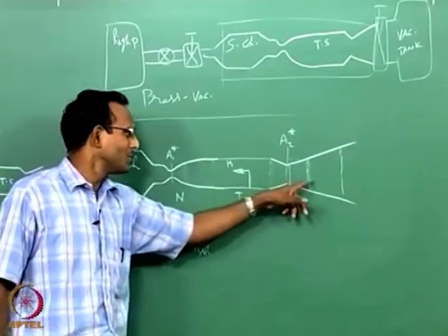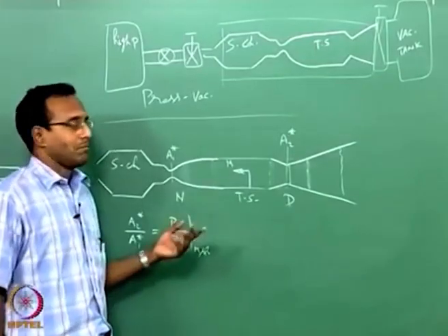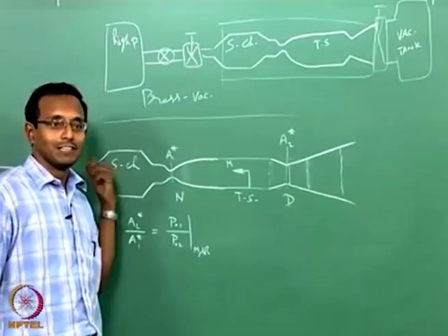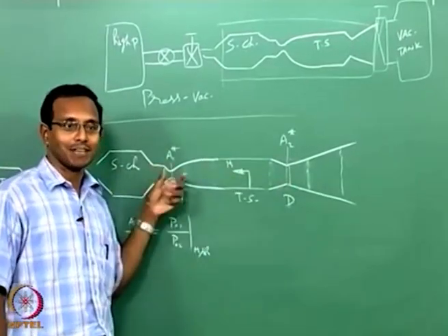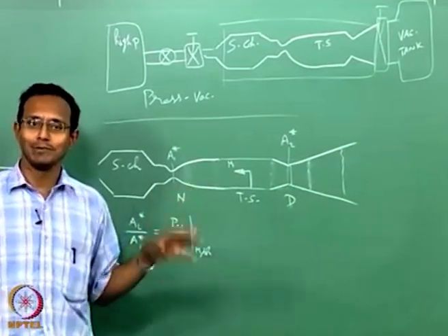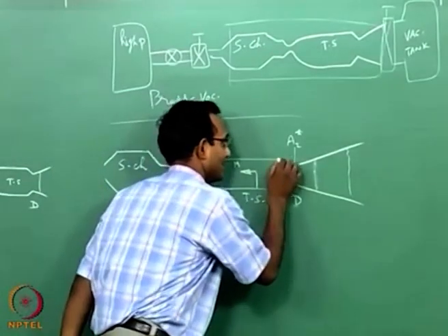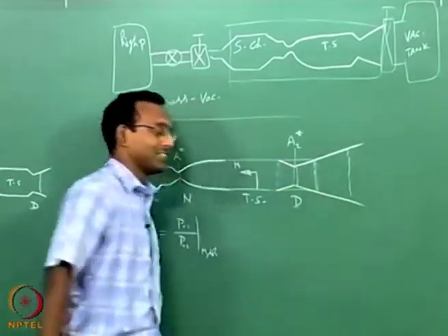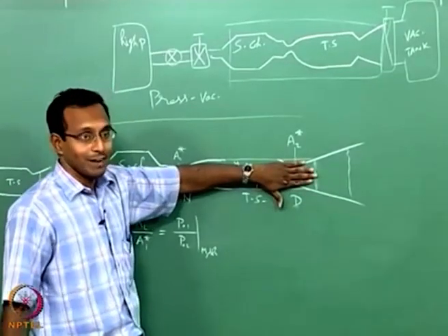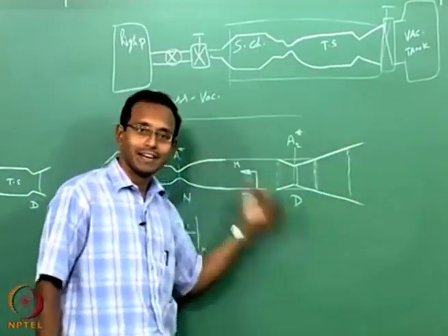Should I always worry about this particular thing? Not always. Okay. Why? By the time I adjust this, if all my mass flow rate is gone from the tank, it is useless to do this adjustment, instead I will get some time without adjusting it. Okay. That is typically the trade off people use, and I have seen tunnels where there is no second throat also, where they just put a straight section and a divergent portion. I have seen tunnels like that also, where I am not really worried about efficiency, I am just going to push the shock into there and take data inside.